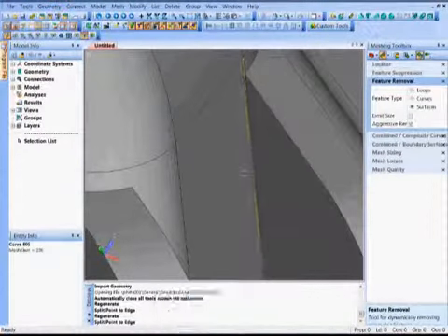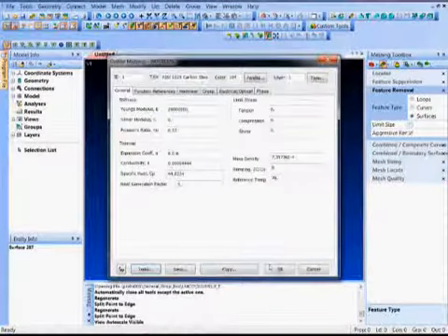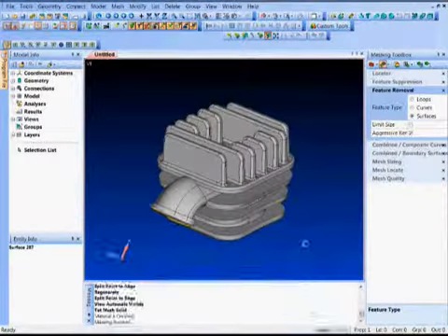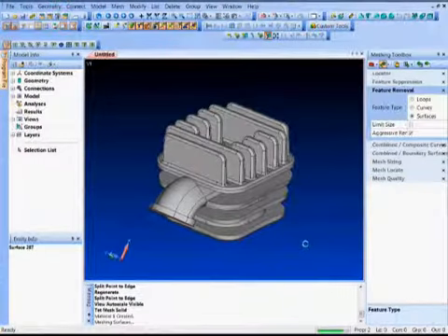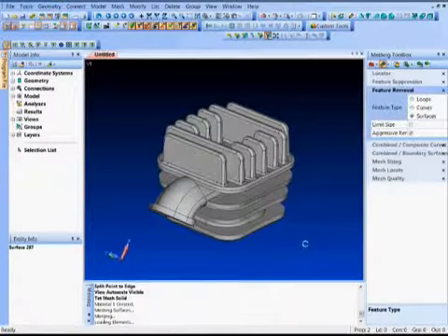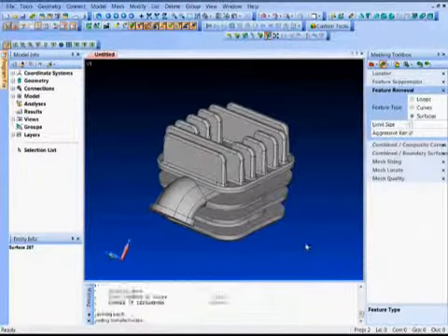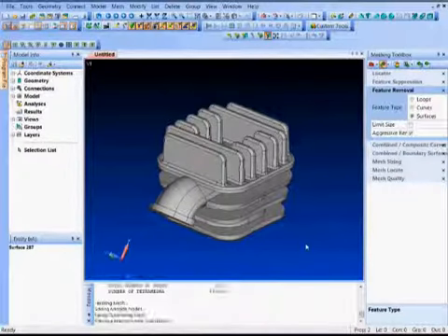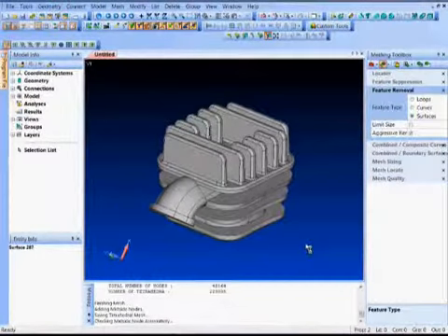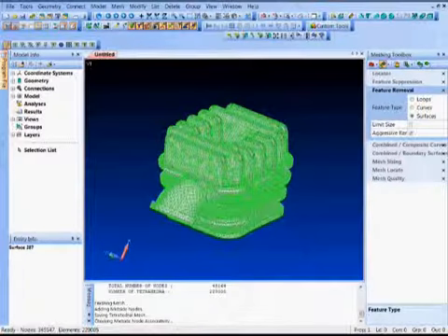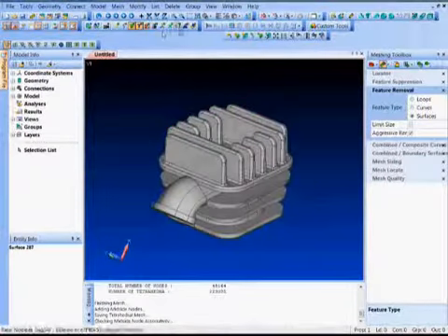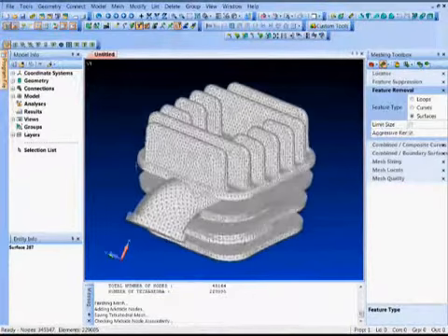Let me bring up the meshing toolbar, and we'll just say mesh solid. Pick a material. Pick the mesh density automatically. Feed it through. The surface is meshed. It's going into the tetramesher. Loading. It's done. Now it's adding the mid-side nodes, hooking everything up to the surfaces for geometry-based loads. Let's turn everything off. And there, we've got a nice mesh.